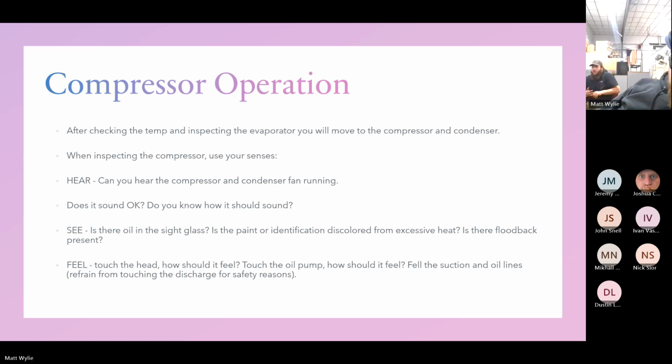Standalone semi-hermetic. Feel the suction and oil lines. I'd refrain from touching so you don't get blisters or burn yourself if it is too hot. Use the back of your hand, then you're fine.